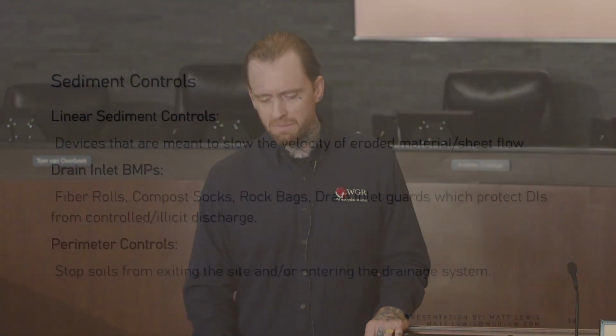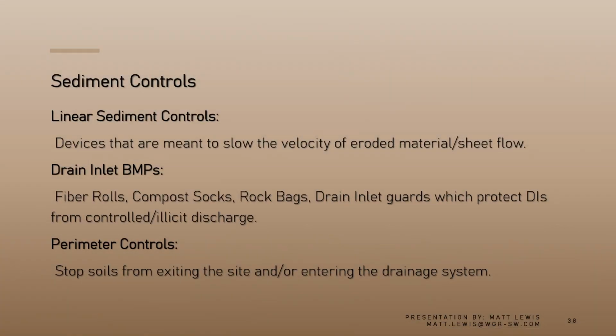So just some basic definitions of linear sediment controls: devices that are meant to slow the velocity of eroded material and sheet flow. Then we have drain inlet BMPs, which can be fiber rolls, compost socks, rock bags, and drain inlet guards, which protect DIs from controlled and or illicit discharge. Then you have perimeter controls, which, as they say, stop the soil from exiting the site and or entering the drainage system. Okay.